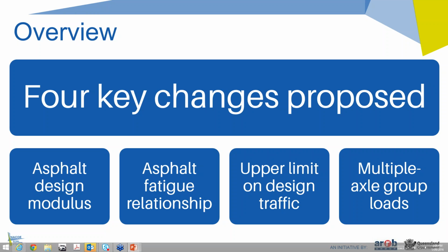As well as benefits in reducing pavement costs, the changes provide a more fundamental design approach with better links between asphalt mix design and pavement design. So the changes are very much suited to the introduction and assessment of innovations, in particular materials like EME2 asphalt or polymer modified binders in asphalt. And that's not easily achieved with the existing pavement design procedures.